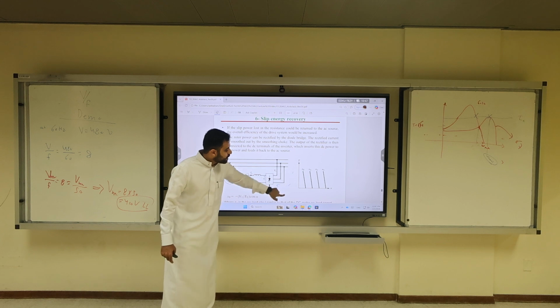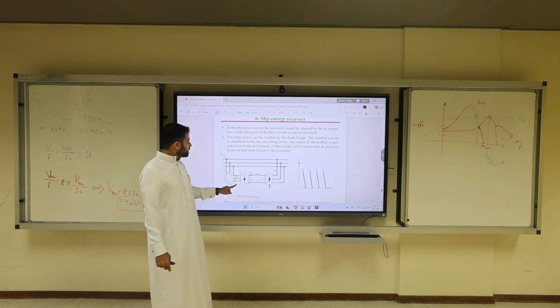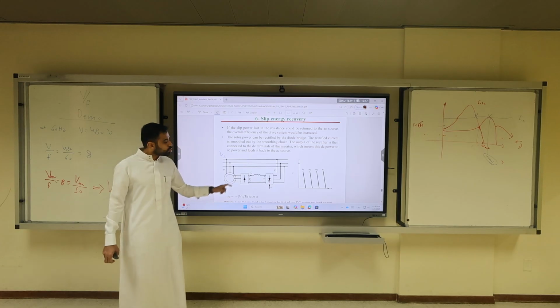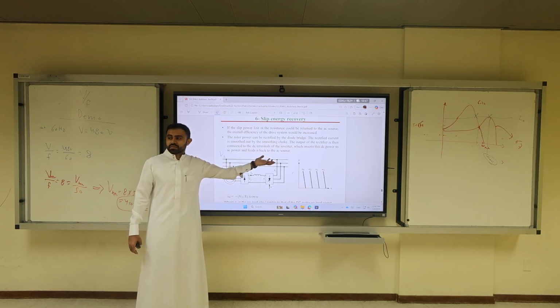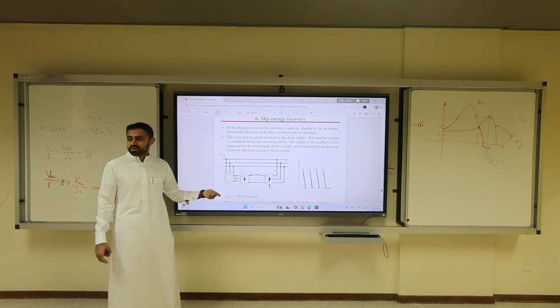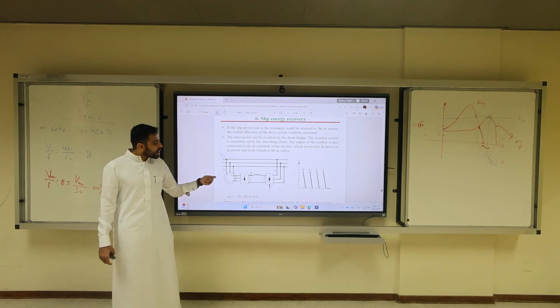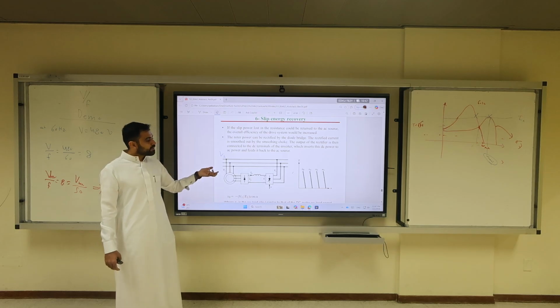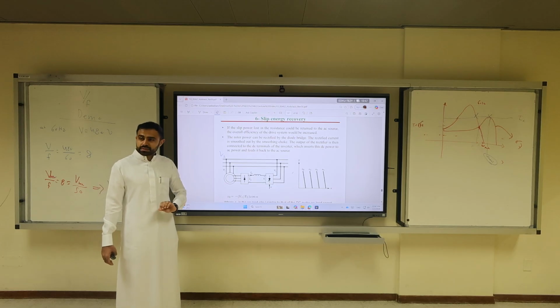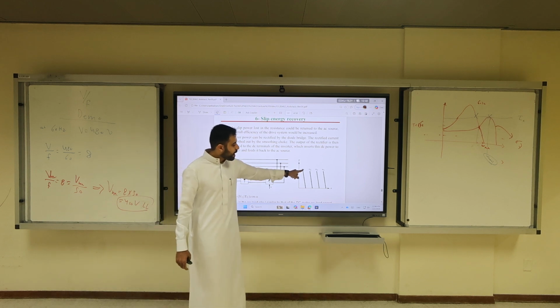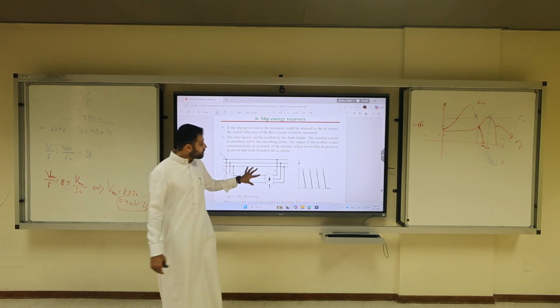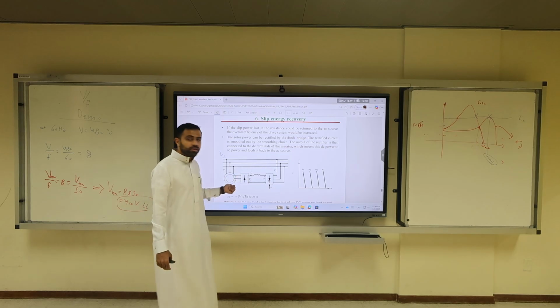So slip energy recovery is, if you look at the rotor, you look here, what do you see? You see just impedance. So this impedance is actually lost in the supply, but we're not losing it, because we're feeding it again to the source. Clear? Yes. So the idea of slip energy recovery, we're not going to do numerical examples, it's just a concept, is you have to control your firing angle to change the effective impedance seen by the rotor.